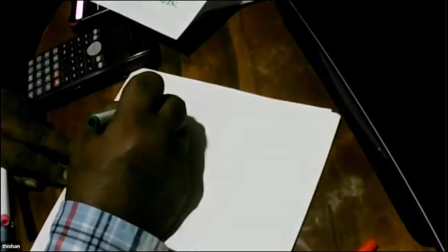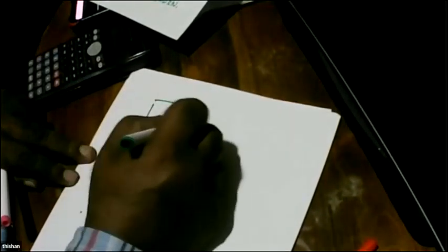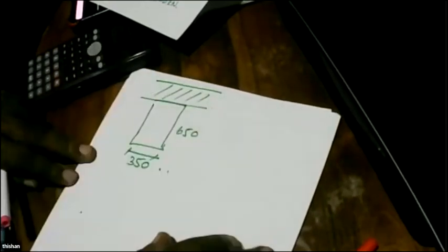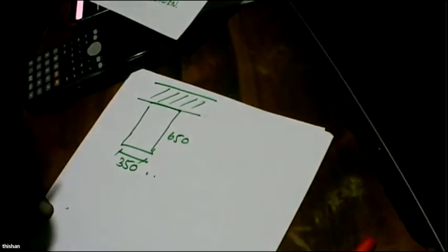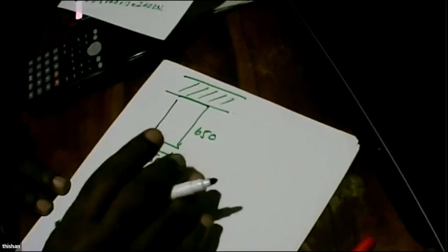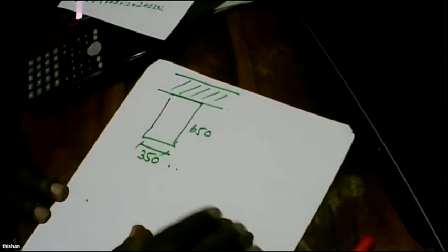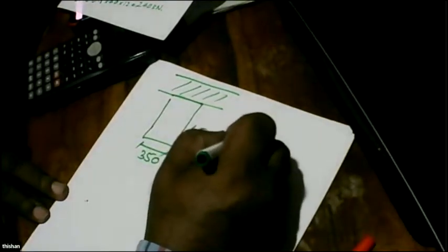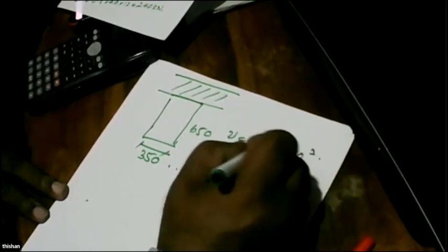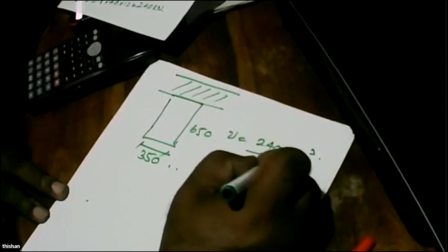Right. Now you can see the shear force is about 240 kilonewtons, and we have a precast beam of 650 by 350, because we might not consider this part, as we are going to cast it in two separate operations. So it will be conservative for us to consider that only the precast beam will carry all the shear force. So if you look at simple v, that is shear stress, that is 240 into 10 to the power 3 divided by 600 divided by 350.